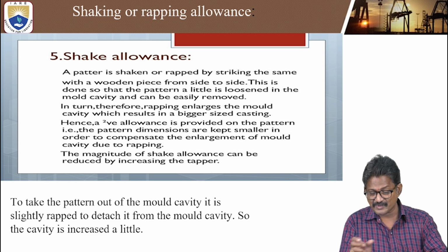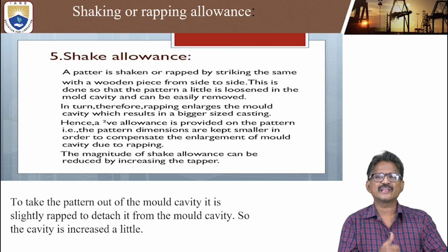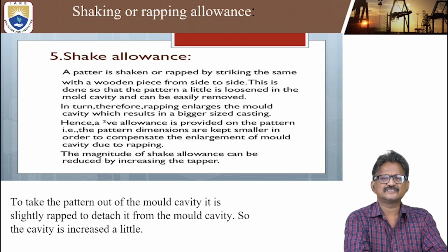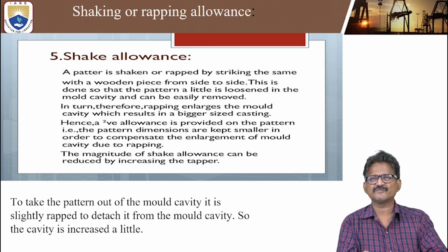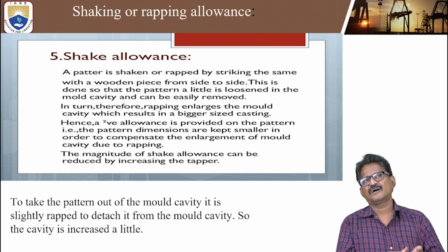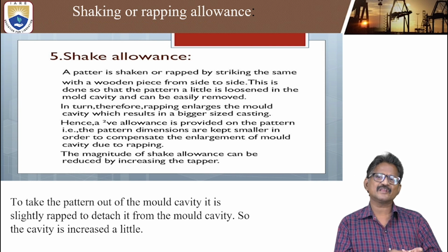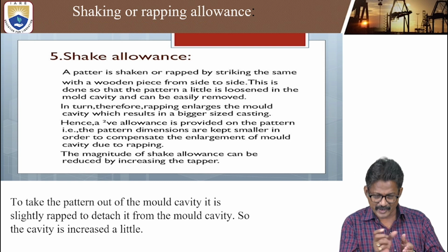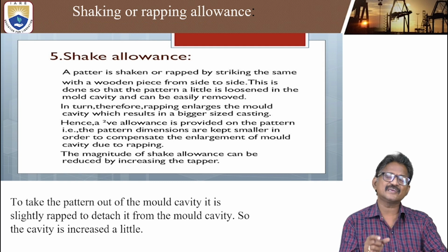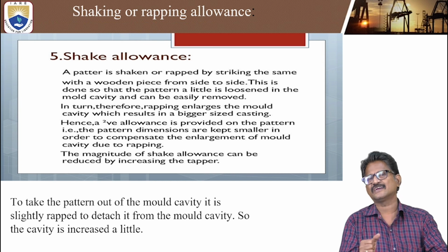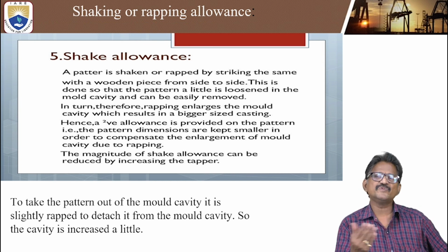Here also the pattern will be shaken, or more wrapping will occur with the rammer and so on. What will happen? Somewhere more pressurized sand will be there, and on some side uneven pressure will be there. Obviously, depending upon the material also, either it may be a wooden pattern, or a ceramic pattern, or a metal pattern, how it behaves for shaking. Automatically by shaking, the pattern will also be changed. If a metal pattern is used, it will withstand effectively. A wooden pattern, by applying more shaking, will tend to move.